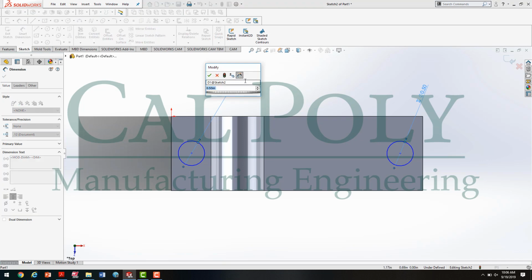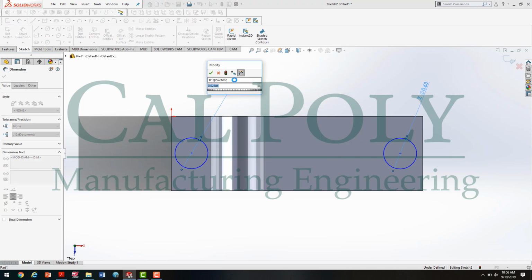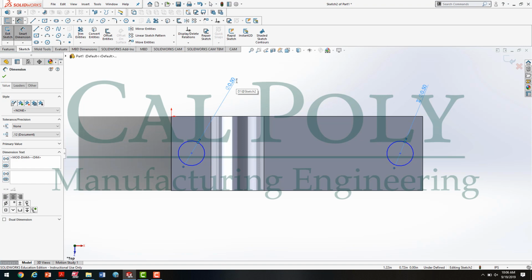So now, this circle relies on this circle's size. So if I was to double click back on the dimension and change it to 0.625, both circles change size. But again, 0.625 is incorrect, so I'm going to double click back on there, type in 0.5. I like to show you extra tips along the way. Hey, why not? So now that their size is specified,